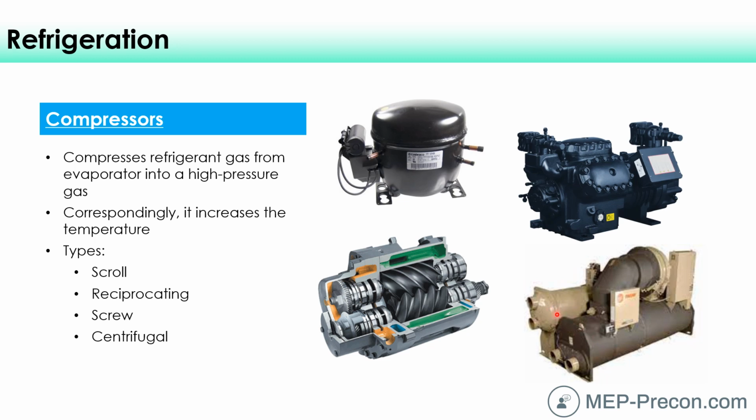And how did I know which one was the evaporator and which one was the condenser here? Because they look similar. Well, this one is covered with some insulation, some Armaflex or Rubatex type rubber foam insulation. And the purpose of that is because this is pretty cold. This evaporator barrel is going to see really cold refrigerant.